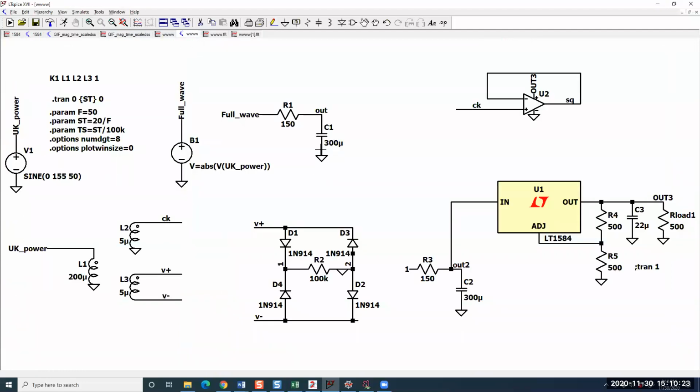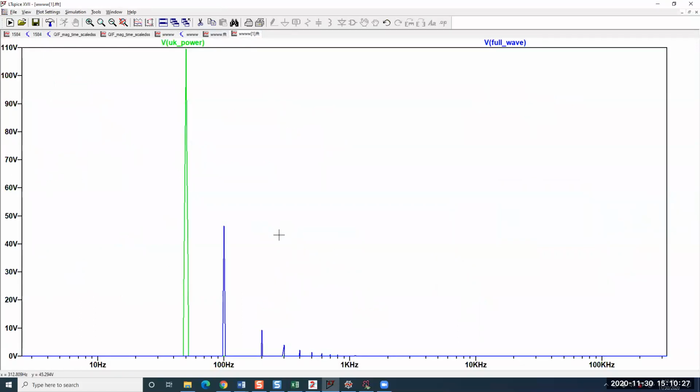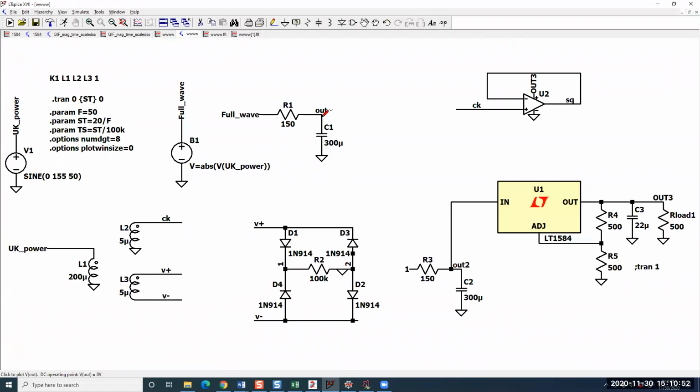Okay. So now I need to convert that to DC. So now I'm on full wave. The 100 hertz is what I don't want, everything above. So I want a low pass filter. I would just draw some kind of filter response like a low pass because I'm trying to get rid of these. Again, I'm trying to capture the DC part, but it just doesn't show up in LTspice.